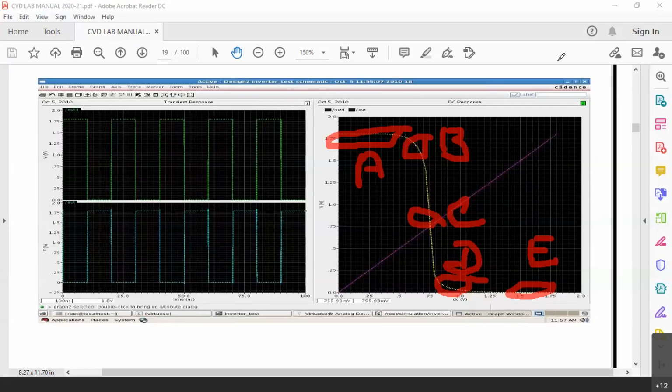So saturation when we refer to MOSFET is different from that of BJT. In BJT, when we say saturation, it means the switch is completely on. In MOSFET, when we say saturation, it does not mean the switch is completely on. The switch is half on. The name saturation is given there because in that particular region, the current across the switch is constant.